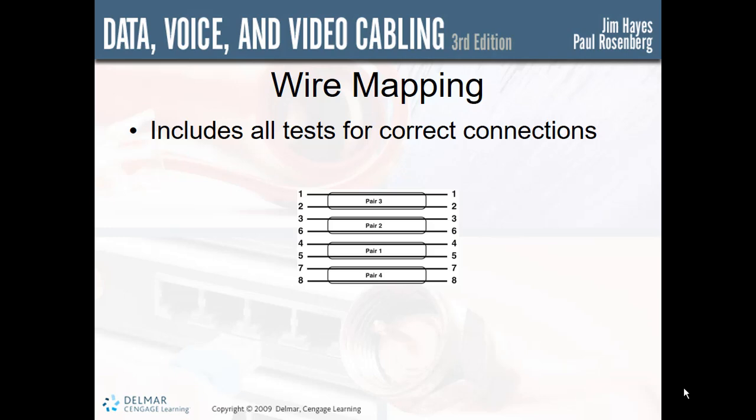Wire mapping includes all tests for correct connections. The correct pairs of wires must be connected to the correct pins according to the color codes defined by the standards, either the 568A or 568B mapping. There must be no transposing of wires or pairs and no shorts or opens. The 568A and B standards may be used for building wiring. The T568B standard is more commonly specified by AT&T. The only difference between A and B wiring is the crossing or swapping of pairs 2 and 3.